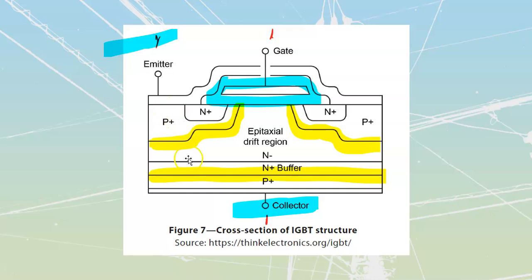As soon as I go through P and N types of materials simultaneously, I actually gain the ability to conduct with fewer losses because I'm going to be basically feeding into my P-type material and then taking electrons from my Ns, combining them across here, feeding back in. So we're just kind of pumping stuff through instead of just pushing stuff through from one end to the other. They also have a much lower on-resistance. When they're actually turned on, the amount of resistance that I see measured across from here to here is much lower than what I had across that channel of the FET.